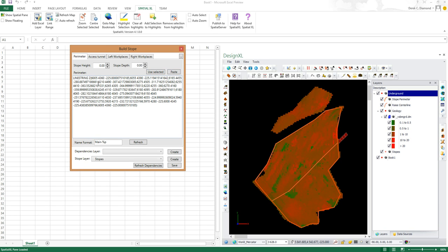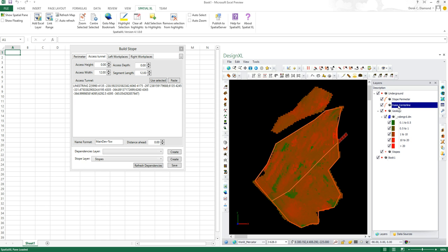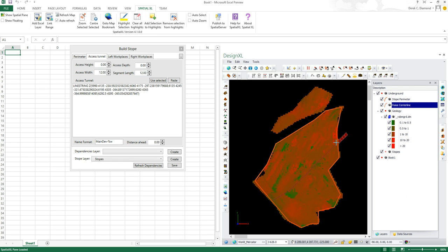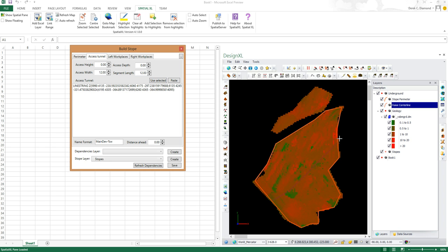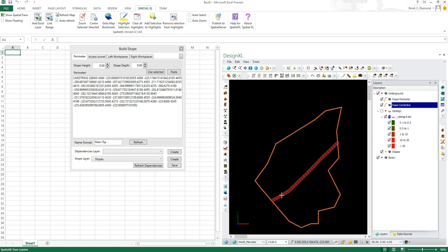I'm going to choose the axis, what we call here the axis tunnel, but it's the raise line again, because I see a different one is being chosen. So I'm going to choose it again by selecting it in this way. I've selected that line string, which is going to be my raise line, and I say use selected, and now it knows that is there. Already, by just choosing that raise line, this tool has put in some development panels for developing the raise line, and I'll show them to you by hiding the block model and the geology. There you can see those particular panels.